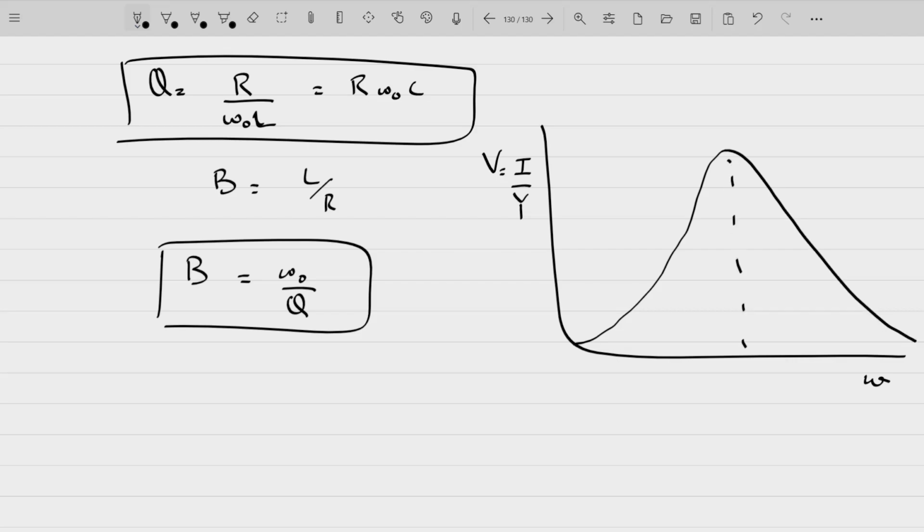So at a particular value, that is the resonant frequency value, the voltage value will be maximum. It will be equal to V equal to I divided by G, or in other words we can simply say V equal to IR. Fine, G तो आपका 1 by R है, तो this is V equal to IR at this particular point. We will be having the maximum value of voltage at resonant frequency, and on either side of it, voltage will decrease.